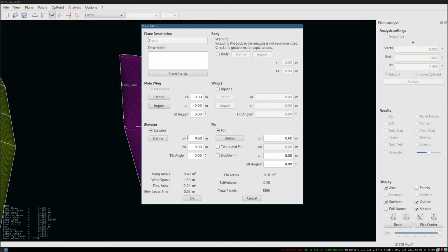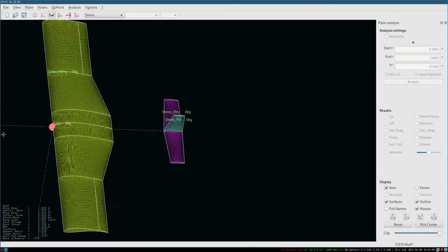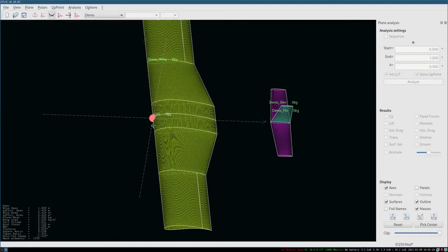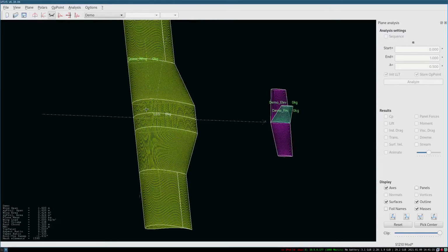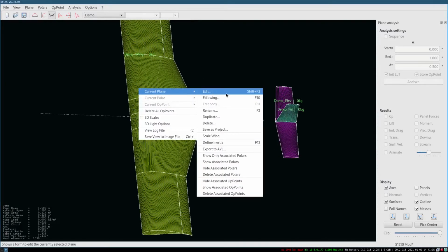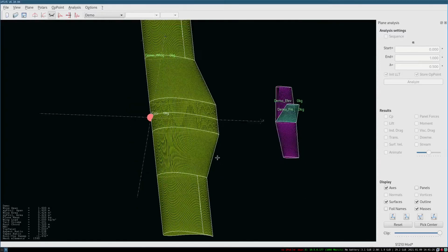So basically this sets the origin point of each wing. So let me just show you what that does exactly with regards to the main wing. You'll see here the main wing currently goes through the origin. If we were to make it, say, go through at -0.1, it would move the wing 10 centimeters forward. So this is how you're going to start defining geometry. And it's especially important to note these offsets when you start fixing the behaviors of an aircraft.